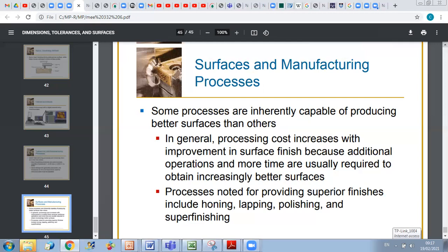For example, in the videos you watched, you have several examples of finishing processes. Honing will use a special tool called a honing stone or a hone to achieve a precision surface. The hone is composed of abrasive grains that are bound together with an adhesive. In general, honing grains are irregularly shaped, and the smaller the grain sizes, the smoother will be the surface of the final product.